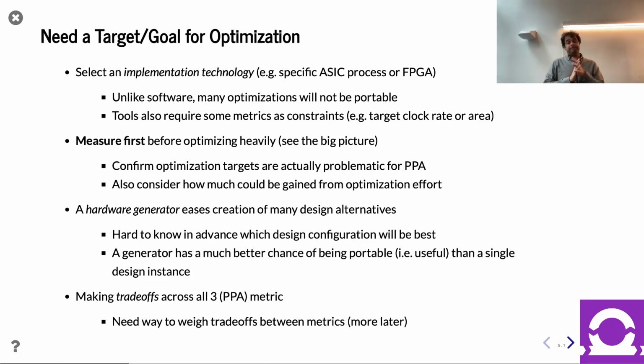Additionally, if you really want to go after power, you can imagine clock gating is not going to get you all the way. You want to do power gating, right? You actually want to turn entire components of your design on or off or change sleep states. At that level, it's definitely an architecturally visible feature, in which case that's going to appear inside the Chisel. So maybe that gets to your question, hopefully. Cool. Other questions?